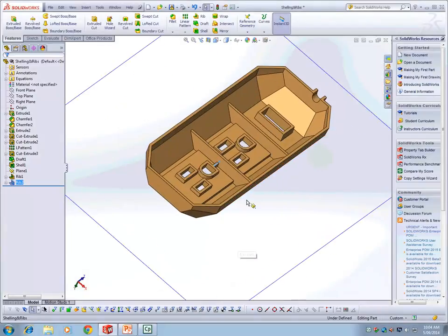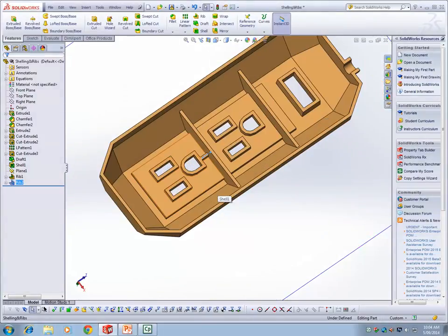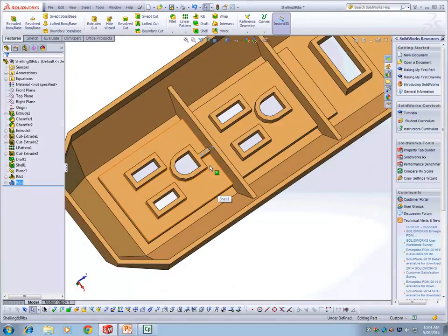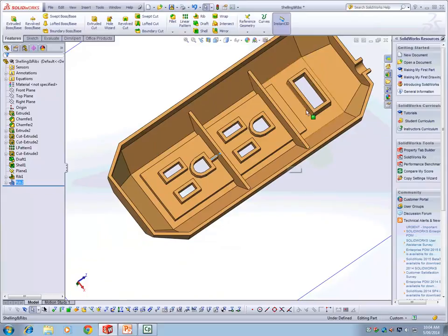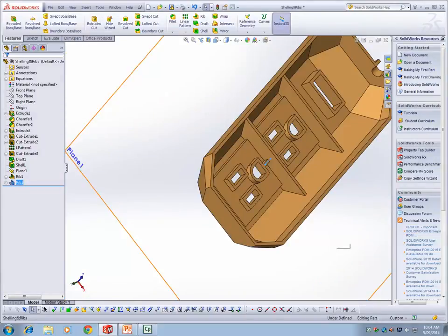You can convert entities on the same plane. Maybe this might be a bit higher. On the same plane, convert this particular edge, removing the relationship to the center, and create two ribs here on this side of the cut and on the other side of the cut here.